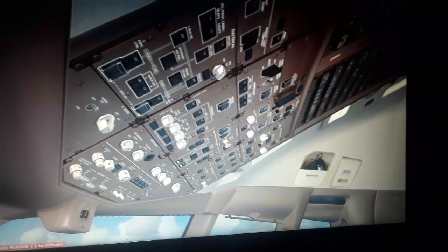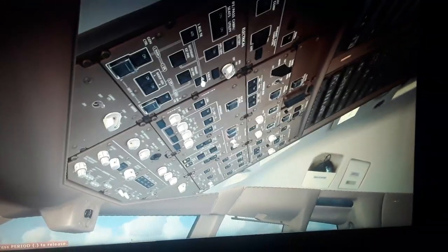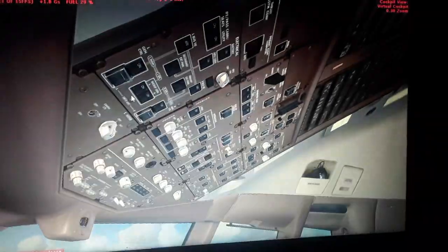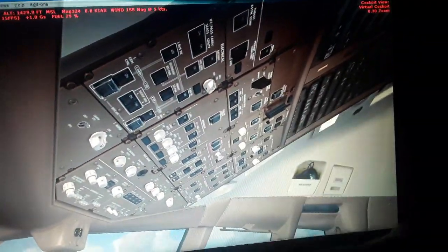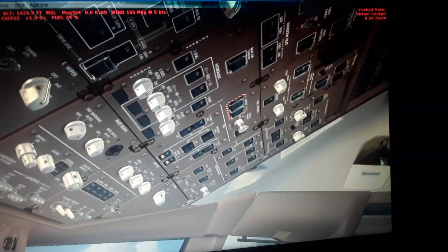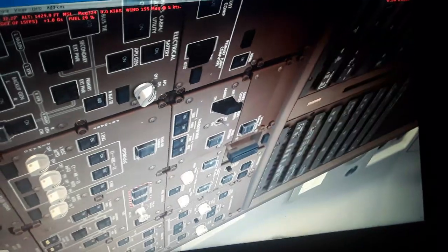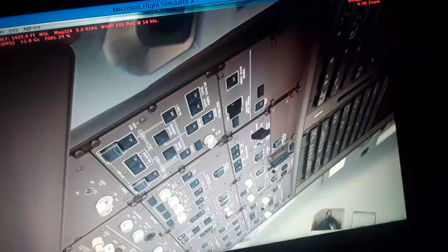with the systems it contains, like the electrical left and right engine electric drive generators, electrical power, hydraulic power using the engine-driven pumps, and the pressurized air from the engine bleed air, or the APU bleed. So we have also the fuel tanks, left, right and center tanks, and the forward and aft pumps. We have electronic engine control for the engine. We have the bleed from the left and the right engine also. So this is some of the systems.